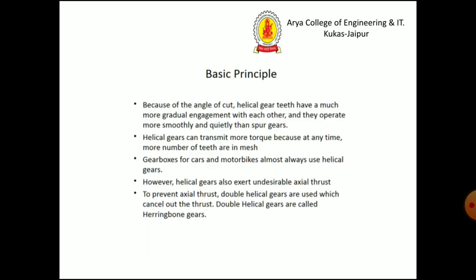Because of the angle of the cut, helical gear teeth have a much more gradual engagement with each other, and they operate more smoothly and quietly than spur gears. Helical gears can transmit more torque because at any time more teeth are in mesh. Gearboxes for cars and motorbikes almost always use helical gears. However, helical gears also exert undesirable axial thrust.